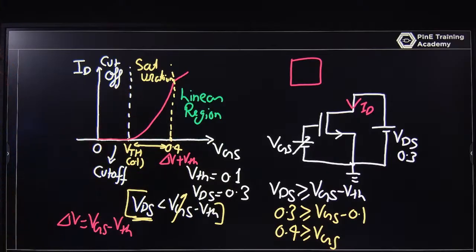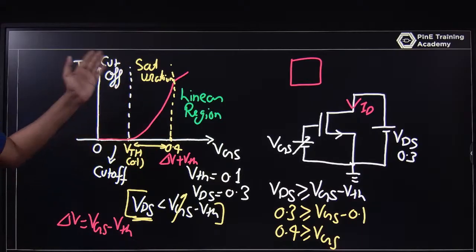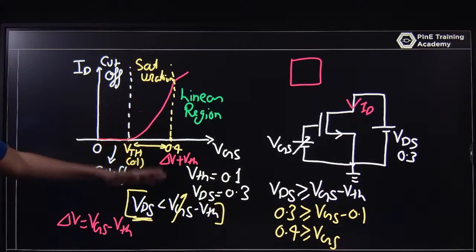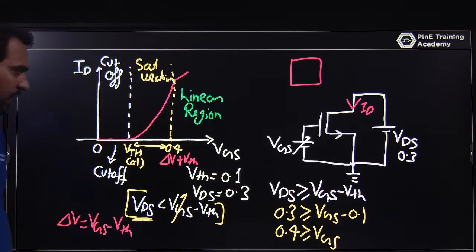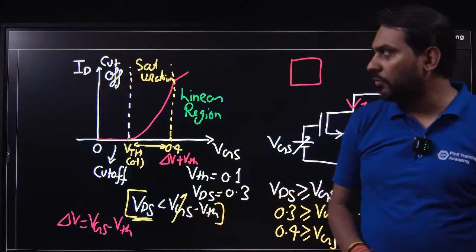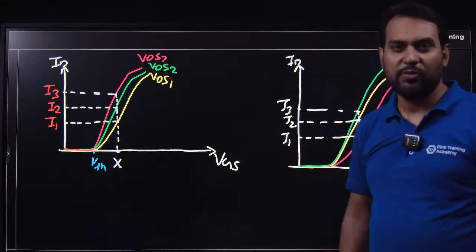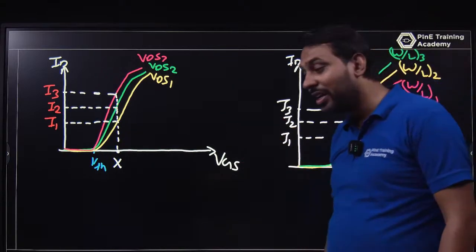If you are good in characteristics, you can explain the common source amplifier, drain amplifier, gate amplifier or any amplifier by this only. Okay, we will work on it. So please be focused on this part, and in the next class we will simulate in Cadence Virtuoso ID versus VGS with respect to different VDS.